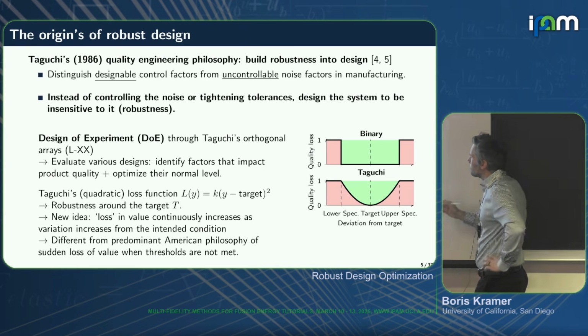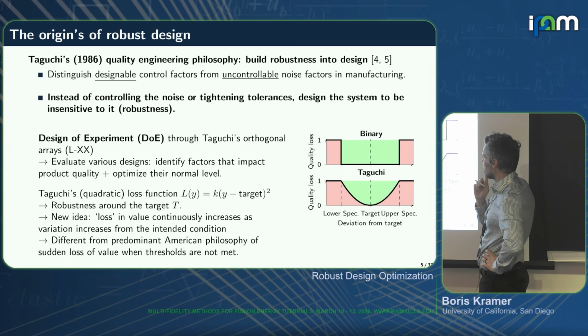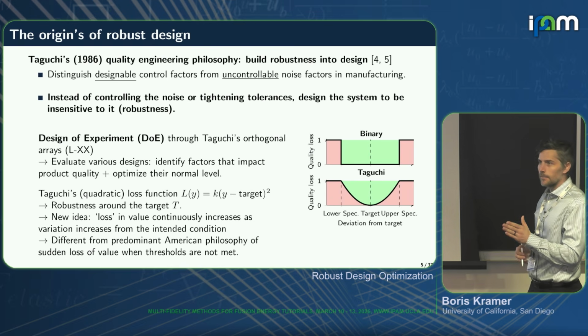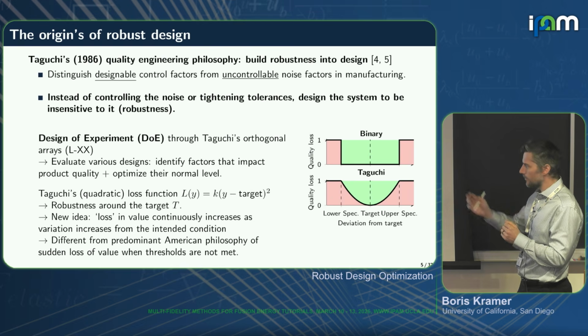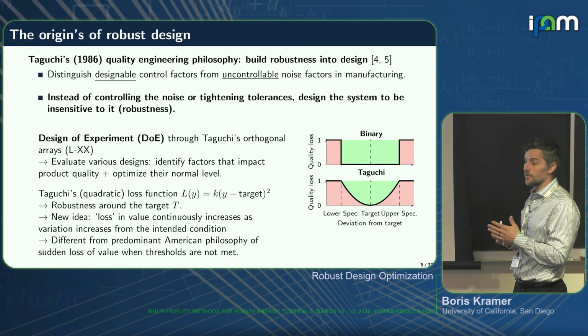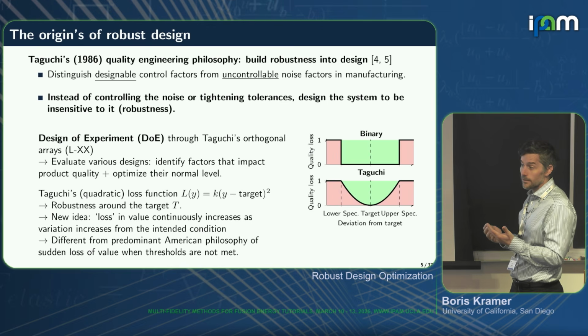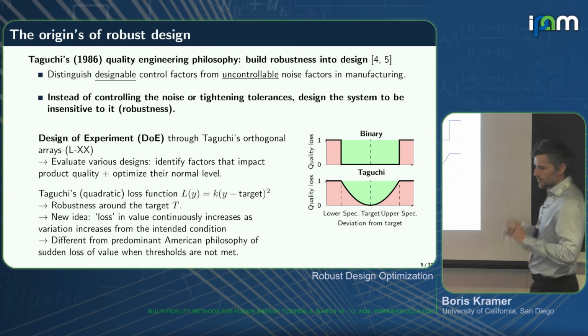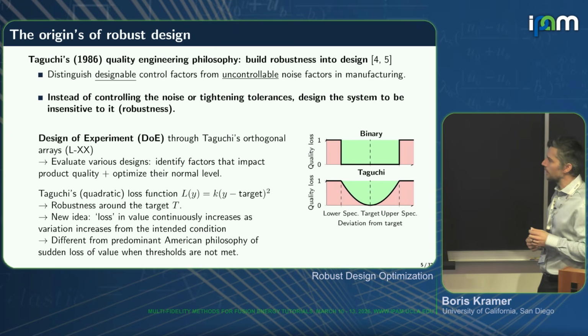Taguchi said, well, from a customer perspective, this is actually not fully true, and hypothesized that a part could be, locally, the quality degrades as you're not hitting the specs, right? But the part is not immediately bad, it just means it has a lower quality. Maybe a customer is willing to pay a little bit of a lower price still. But eventually, once you totally miss the spec, then you're off and we're going to call it back.